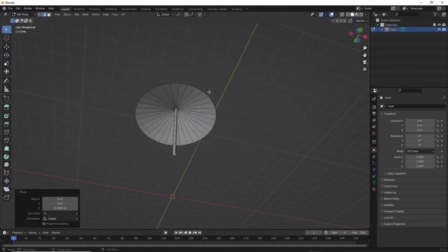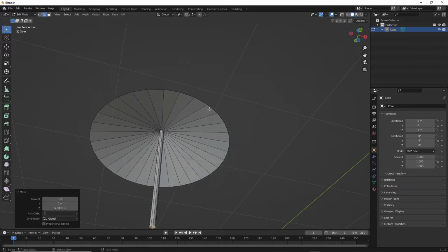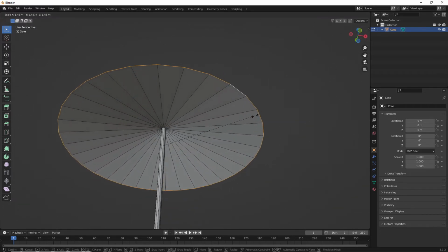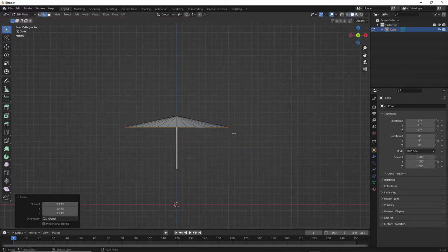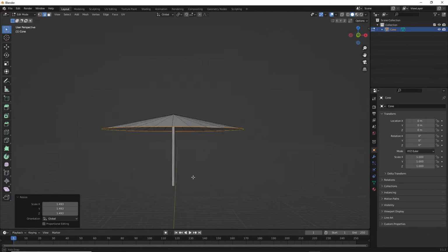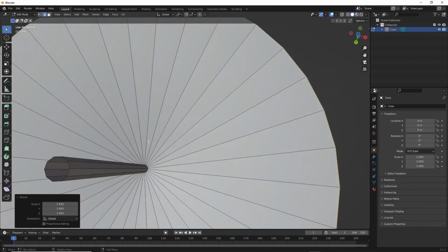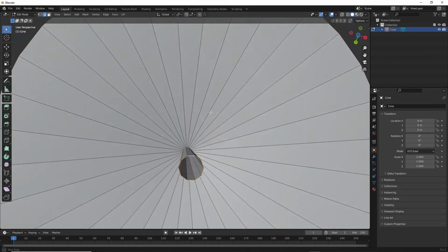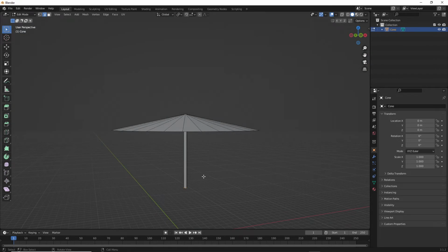I think we should make this a little bit bigger. So I select this one, hold and select in edge this side here, and I scale this a little bit more. I watch this, yes. And here I want it a little bit longer now. Same goes here. I go close to this one, hold and select this edge, and then a little bit back, and I extrude this again. No, I don't extrude. Oops, Control Z, not extrude. Then I grab and set and make it a little bit longer.